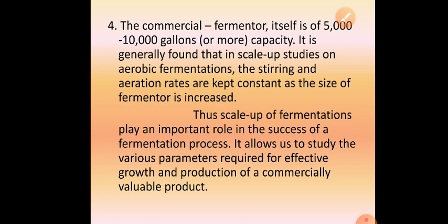We slowly go on increasing the volume of the fermentation medium, and you go on increasing the production. And when you go on stepwise increasing the volume of the medium, you actually are transferring the process from a small lab flask to a laboratory fermenter, then to a pilot plant scale, and make sure that all parameters can be controlled.